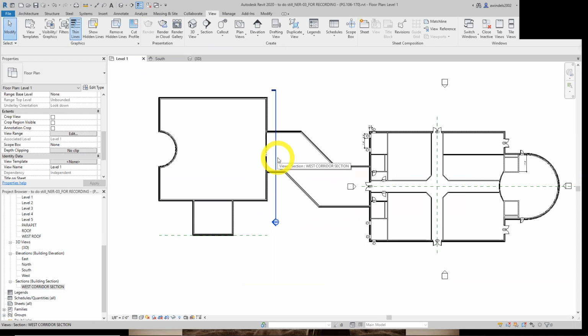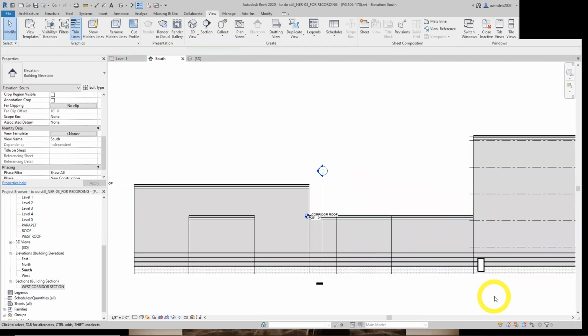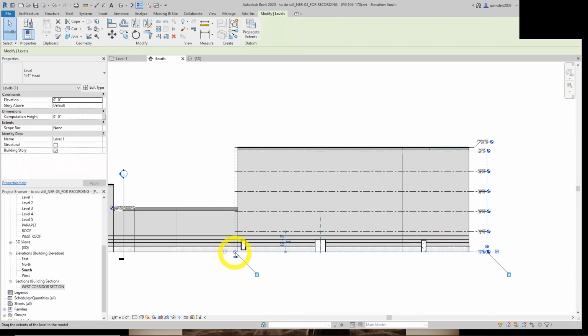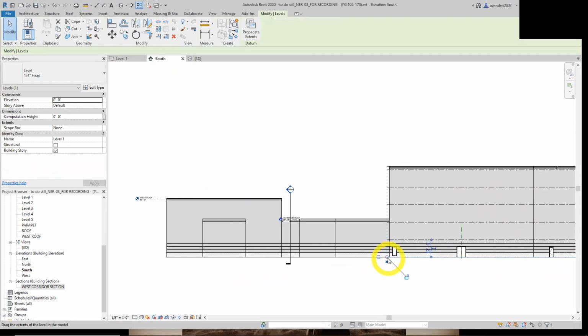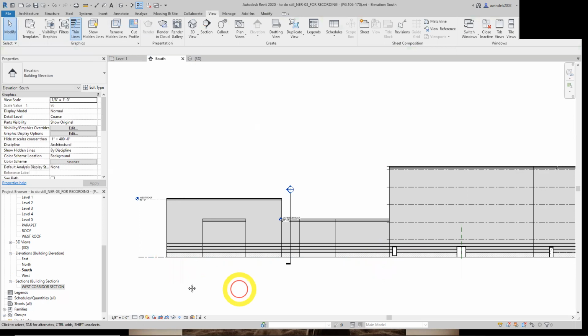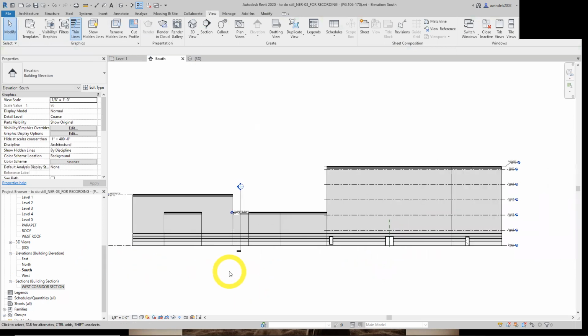So we're going to go back to the south elevation view of the level, and it wants us on, I believe, step 9. We want to make the left grip of level 1 all the way to the west side. So this level 1 is the whole building. Let's unlock it here. Unless we want to drag all of them, which we don't. We'll drag just this one. Let's let it run into that. It'll recognize it and snap to it vertically. Boom. Level 1 over there. We just want to leave the icon of its annotation over there.